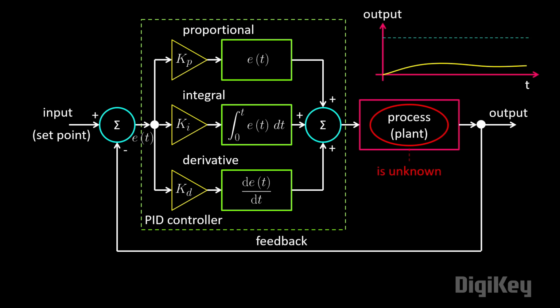You set Ki and Kd to 0 and leave Kp at some low value. You increase Kp until the output oscillates with some steady state offset. You then increase Ki until you correct the steady state offset, even if that means more oscillation. Just make sure the output does not become unstable and oscillate out of control. Finally, adjust Kd to remove the oscillations. At the end of the process, you should have an optimally tuned system.